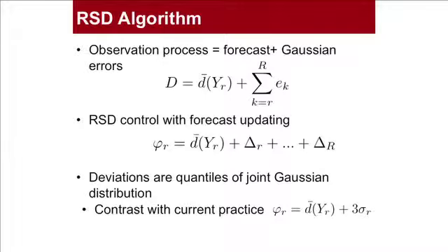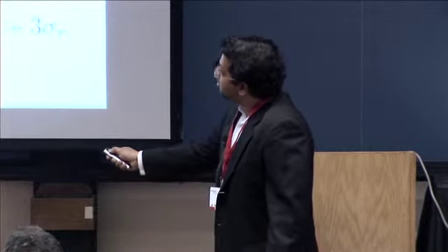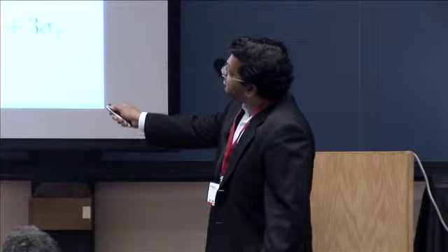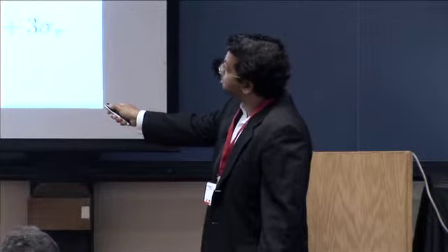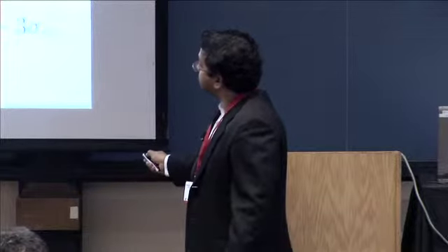the rule that you need to use to optimize your grid is something like that. At every market, I'm going to schedule whatever I forecasted my deficit to be, that is load minus wind, plus some deviation amount. This deviation can all be pre-computed. They only depend on the statistics of your forecasting. Now, these deviations are specific to each location, to each forecasting system, and the performance of that system. And compare that to something like this, and you can see there is a difference.